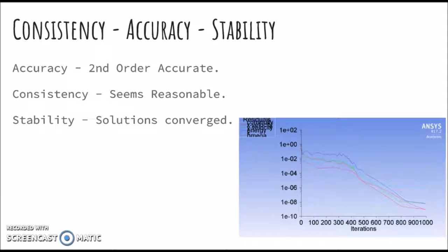The flow, turbulent kinetic energy, and specific dissipation rate of the fluid was all solved for using a second-order upwind discretization. Although these selections are more computationally expensive, they are required in order to converge a more accurate solution for the compressible airflow and accurately predict the drag. Overall, this solution is second-order accurate.